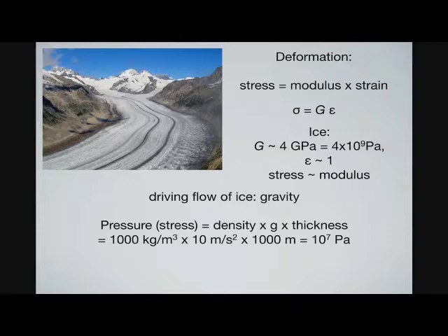But then here we said from Hooke's law, the modulus is of the order of 10 to the 9 Pascal. So there is a contradiction, and that contradiction was realized, as I said, when people started deforming metals, that the ideal elastic constants are such that you should never be able to deform anything, right? You should never be able to, this is like 2 orders of magnitude. It's actually quite a bit worse, right?